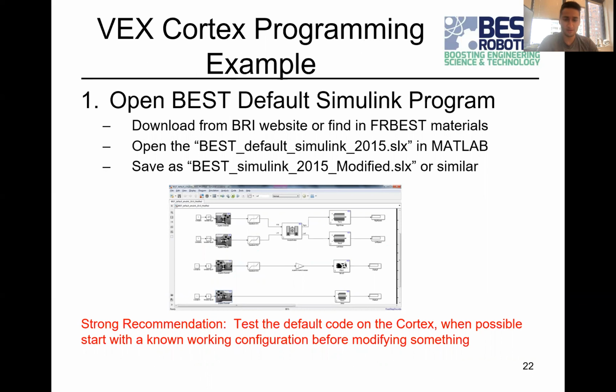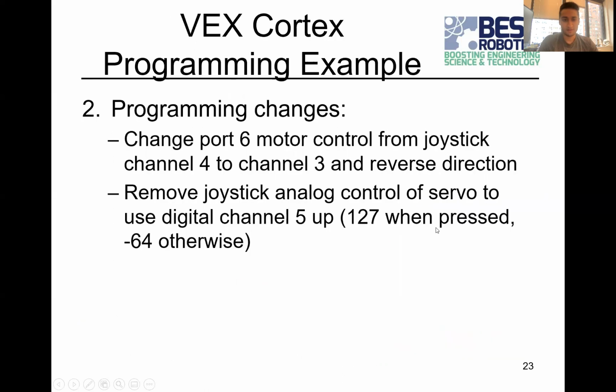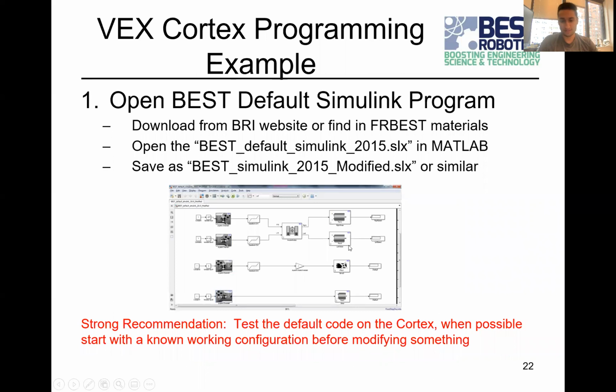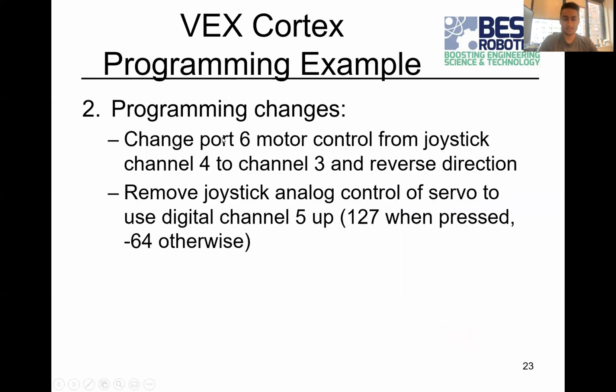When you open the VEX default Simulink program, once you download it, it'll just open as a Simulink file. It has all these weird new sorts of blocks. That's what you downloaded from the VEX plugin. And once you have that plugin downloaded, all of these VEX blocks you can find under the library browser. So let's say we want to make a few changes to this. This is just kind of like a control system. You have these controls feeding into the motors from various input sources. So let's say these are a couple normal things that you would probably do as you're testing your robot and coming up with your control schemes.